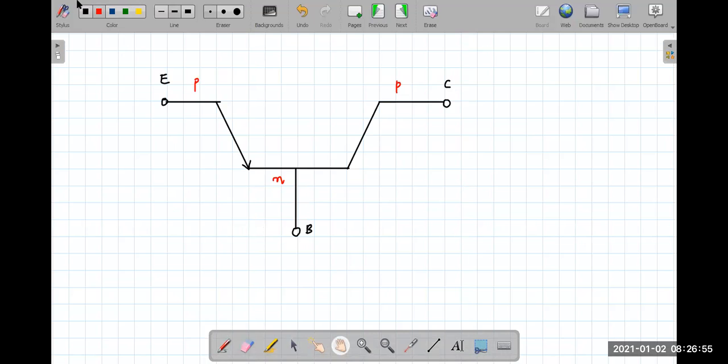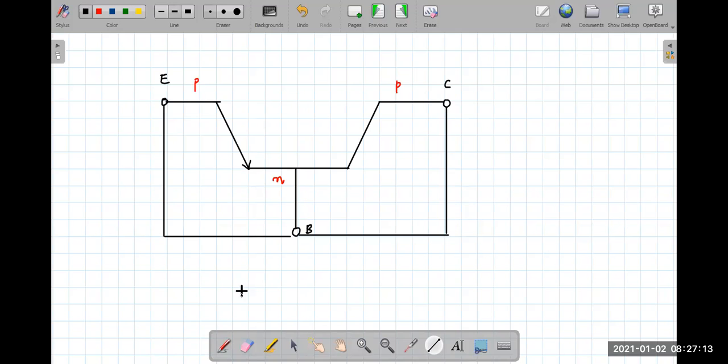So coming to the active mode connection, here, look at the terminals. Let me draw a terminal from here. These are the types of connections which we can make. We are supposed to make the connection in this manner. We said that we have chosen base as common. You see here, base is common to both of them. Understood? So just to make sure that base is common, we'll ground the base. We have grounded the base.